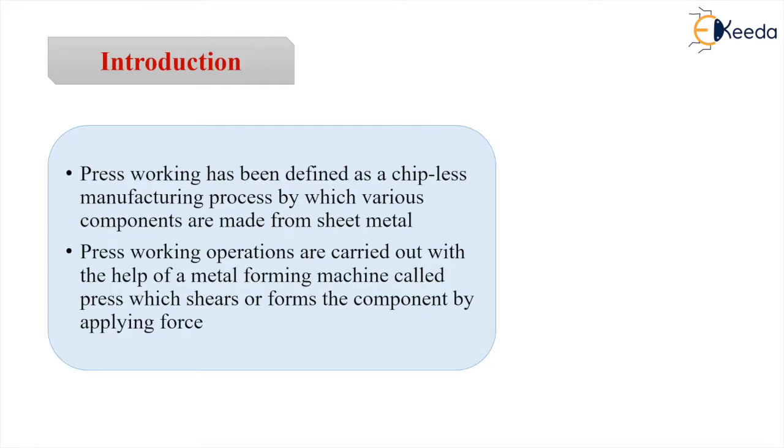forming operation. Here in cutting we are inducing stress in the material above the shear strength of the material, or above the ultimate shear strength of the material. When the stresses go beyond that, the cutting will occur or shearing will take place.